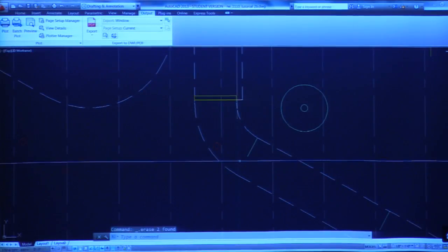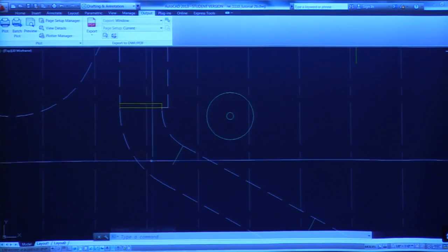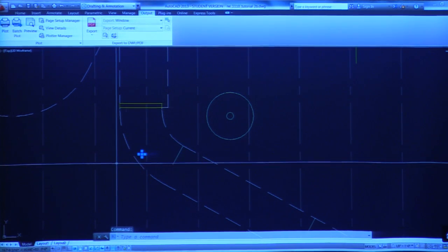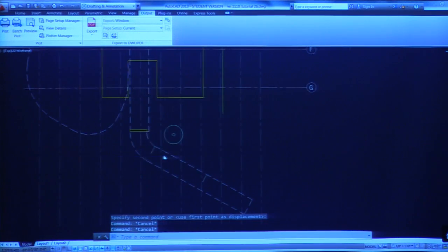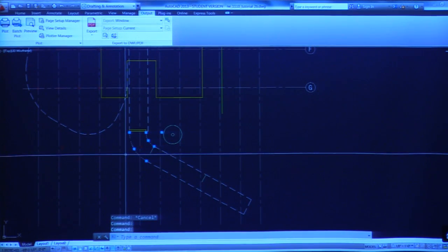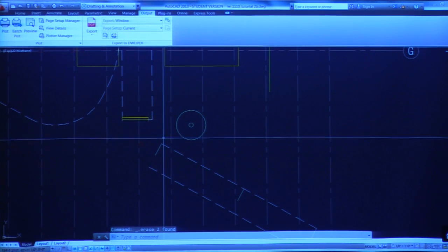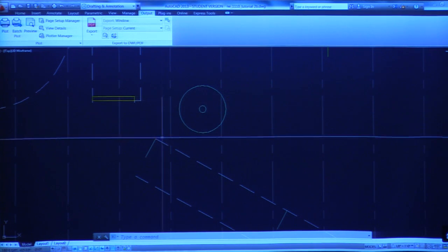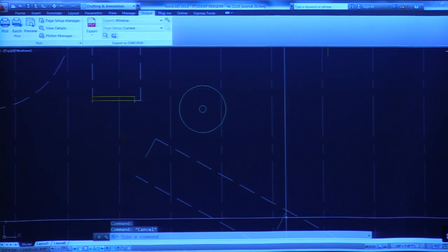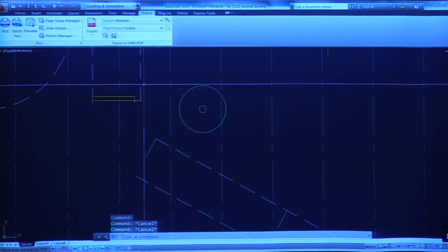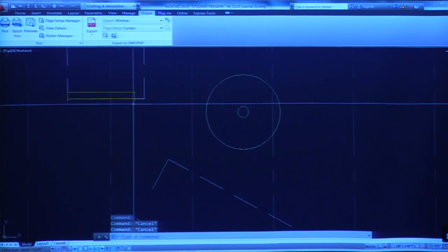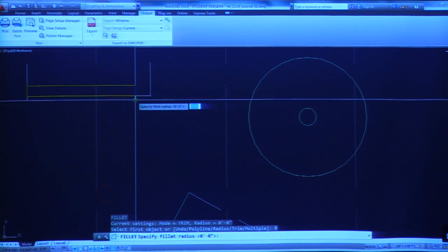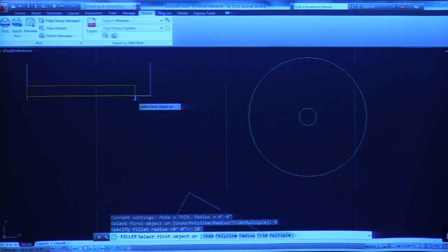So that's a way to locate that column. Let's pretend, for instance, that column ended up here. I'm going to show you how I got this curve there. How that was done is through triangulation. Say even the tree, you're able to set this point, and you're able to set these points down there. Then you do the fillet command again, and you adjust the radius. So you type radius 20 feet or so, and